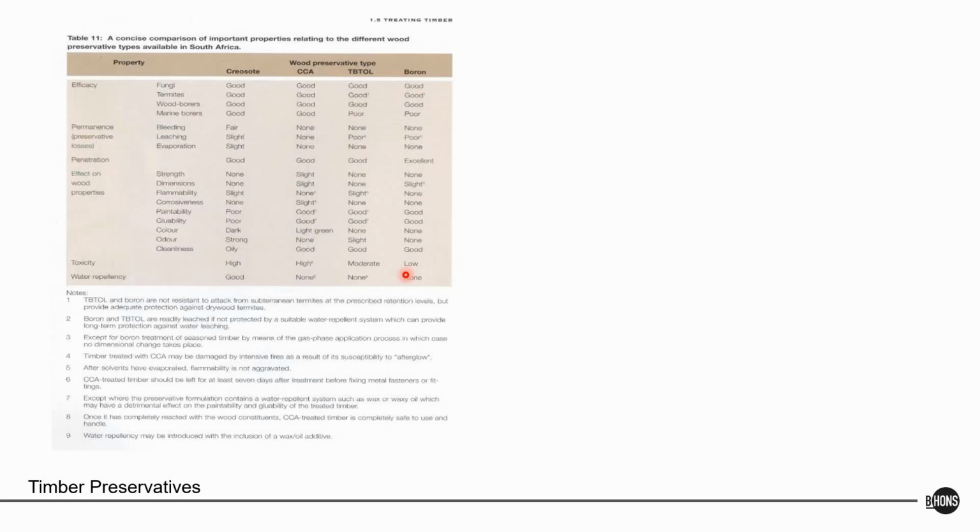There's a lot more information on that, but understand where you're using it to understand how much you actually need to use. Remember, when you're using it indoors, significantly less preservative is needed than when you're using it outside. And typically also when you're using it on the southern side of the building, where it's more shaded, you can carefully use less preservative, or it will last longer. So think carefully about that.